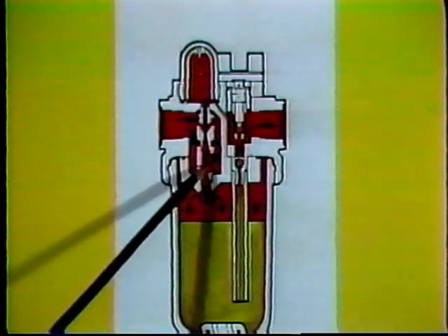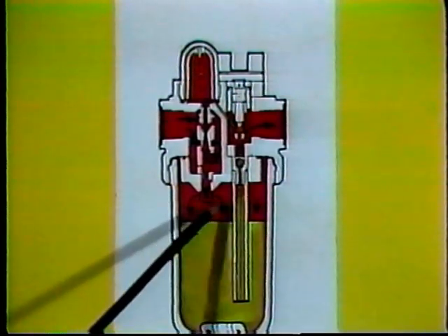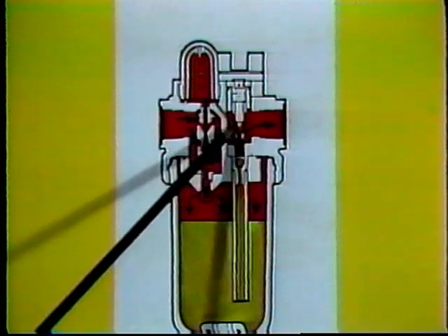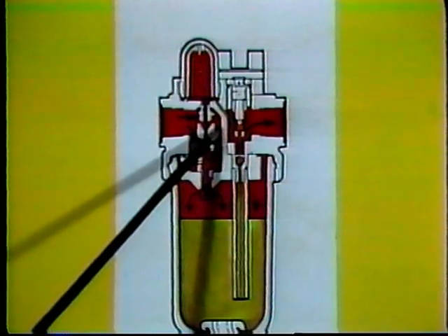Since pressure is then higher in the bowl, oil is forced up this pickup tube and past this metering adjustment. Drops of oil drip into the venturi section here, where they are broken into fine particles, mixed with the air, and carried to the outlet.